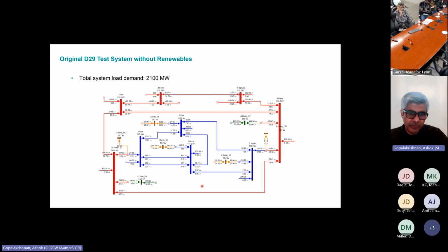We can tailor these studies to consider the local backup as well. For example, breaker failure protection would be considered a local backup, and you can run these studies to measure and check those time intervals also, if you need to do that. So I hope that was helpful.